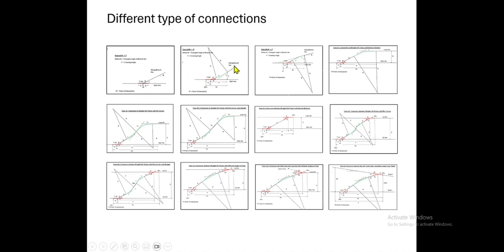In the other situation, suppose the siding line is coming here and its extension meets the main line at some point. But when you measure that inclination angle, it will be more than the angle of crossing. Suppose you are using a 1 in 12 crossing, so the angle of crossing is 4 degrees something, and this is around 6 degrees. It is more than that. In this case, we cannot connect it directly, and necessarily there will be a connecting curve.